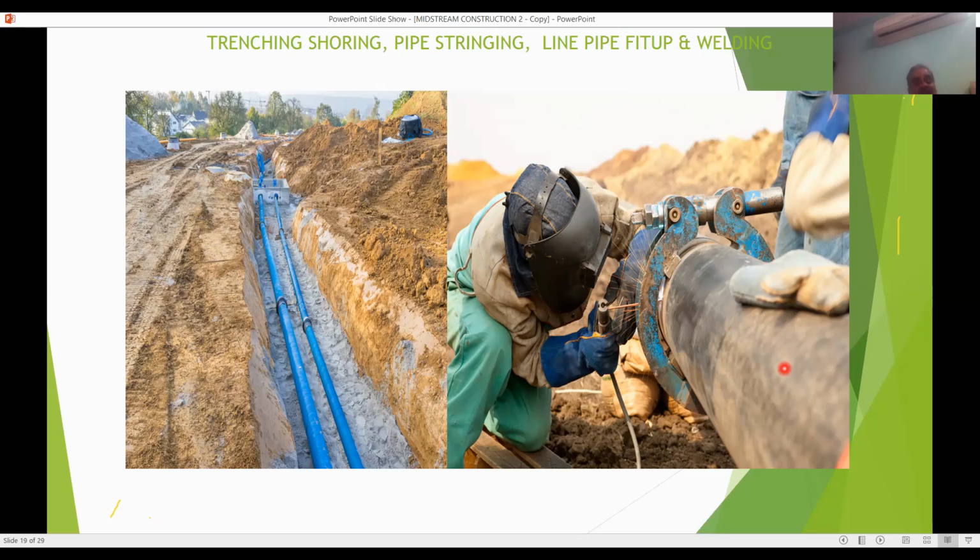This coating should not be damaged. So you see this pipe end, around 200 mm is bared and cleaned. Then both sides are cleaned, and with the support of a pipe clamp, they are joining both pipes. Okay. Then they start welding. Because if foreign material is there, a lot of imperfections and defects will come during the course of welding.